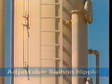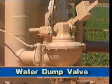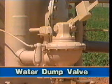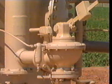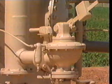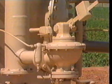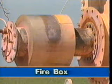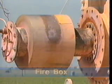within the heater treater. The water dump valve operates either by gas provided from a gas supply line or mechanically by a lever attached to a diaphragm. This diaphragm opens or closes the valve depending on the amount of water in the line. More water opens it and less water closes it. The firebox houses the gas burners which provide the heat source for the heater treater.